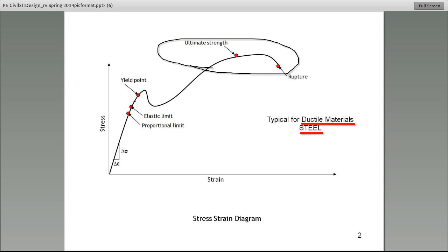All right, so ductile materials that have this kind of typical stress-strain curve, what we know about them is the fact that the initial part of the stress-strain curve is linear. Remember, guys, we talked about that last week. You see that red line? That is the segment of the stress-strain curve below the proportional limit. That means, from the lecture last week, we know that that segment of the stress-strain curve is indeed linear,